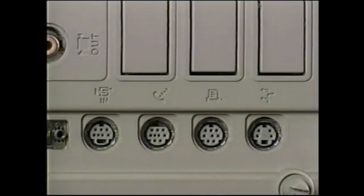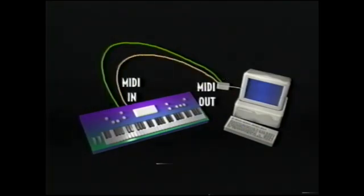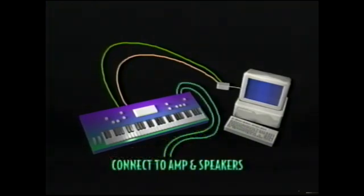Now plug your computer interface into your computer, into either the modem or the printer ports. Now connect the MIDI out of your keyboard into the MIDI in on your computer interface. Connect the MIDI out of the computer interface into the MIDI in of your keyboard. Remember to turn local off on the keyboard. Plug the audio outputs of the keyboard into a mixer amplifier or plug some headphones in and you're done.